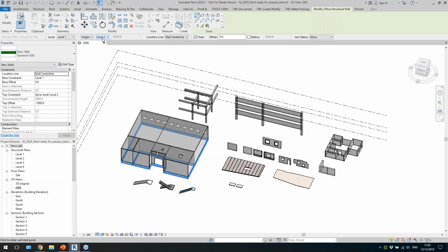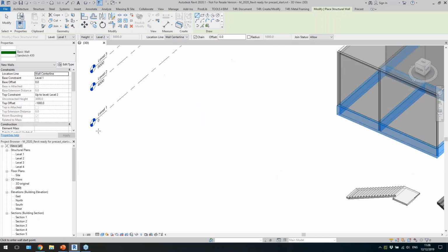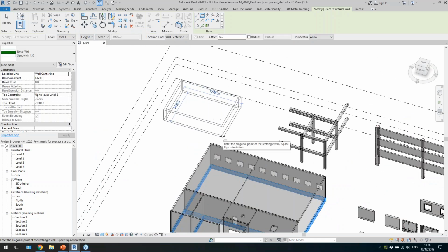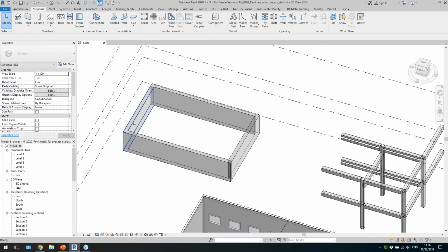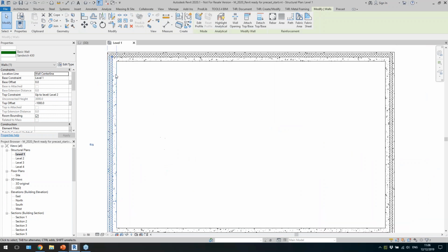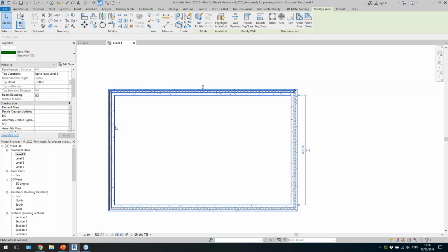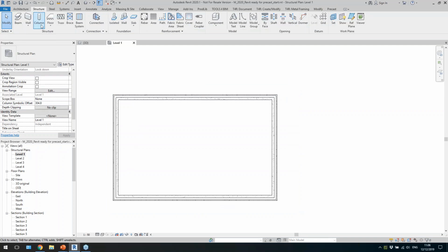I say that it goes from one level to 2 levels. As you can see, I have some levels defined with some elevations. All right, so let's use them. Let's create just a rectangular shape of walls. So I have now 4 elements created. If we go to the plan view, we'll see that this is a 3-layer wall. We have all the information in them. We have some analytical model created as well, and if we select each of them, we have the area, length, and volume information at once, right?